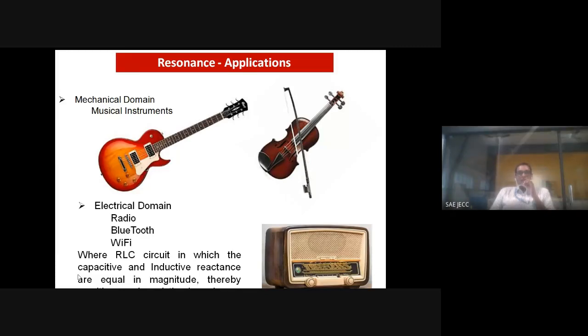The different strings provide different modes, because the thickness, the material, and the cross-sectional area will be different for different strings. That is one option to change the frequency. Then another thing is, you change the length between the supports by putting your finger at different places. That means the distance between the supports changes, so naturally the mode will also change.